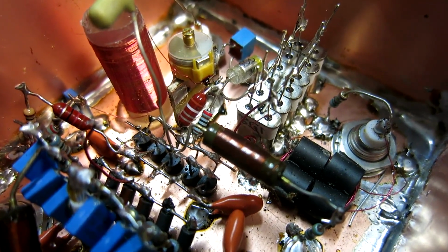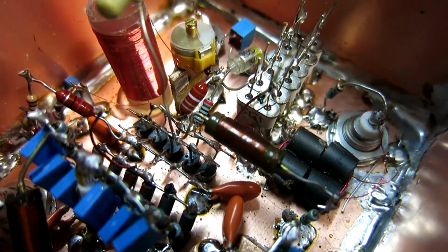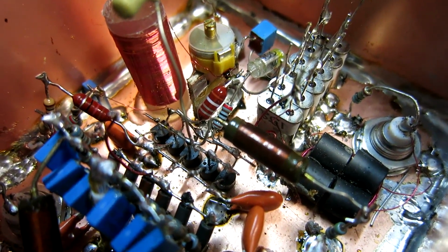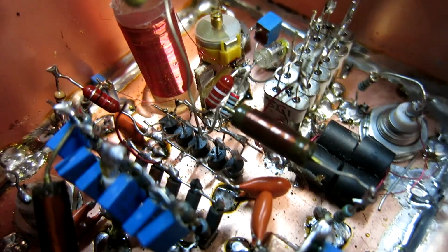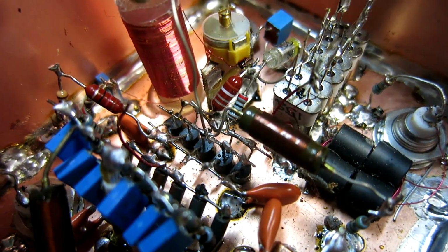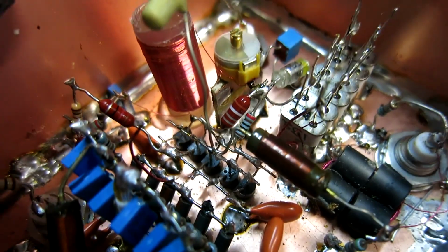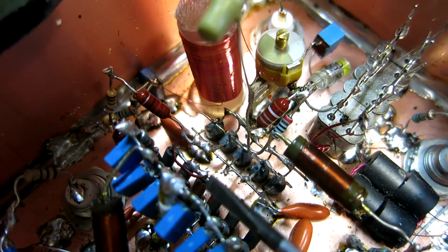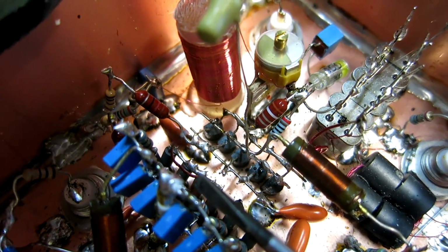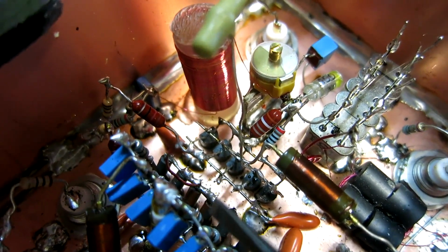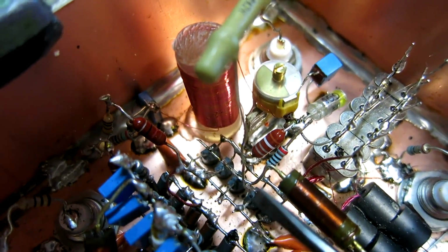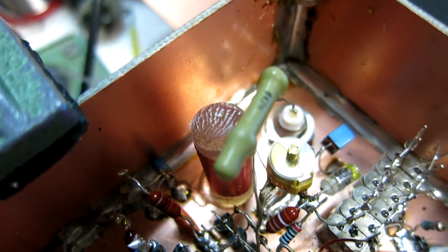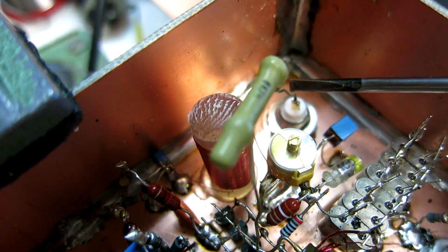I will try to improve performance of this selective amplifier or oscillator. To that end, I first study the input stage. I have cut the connection between the J FETs and the first stage bipolars, and then connected the emitters or the sources of the FETs through this big capacitor to an extra BNC connector here.